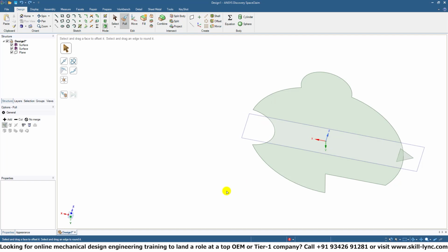So what I would personally do in this situation is save a different set of files. I'd save a working file, which has all of my helping geometry or reference geometry in there that I've used to actually create the final model. And then I'd have a separate file with the final model itself, where I remove all the additional helping geometry or reference geometry just to have a clean 3D model.